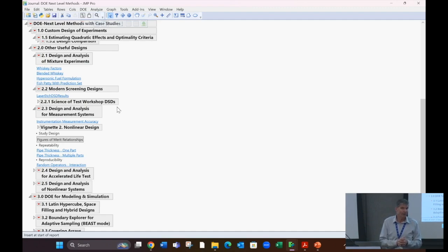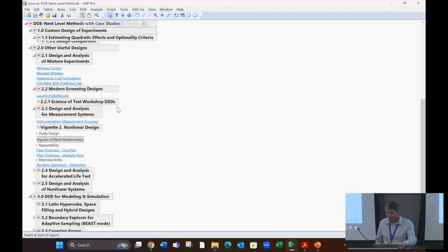And we would like to quantify how good our system is, right? A lot of people in the DT world in particular are very much on top of their gauge repeatability and reproducibility. Repeatability is, if I measure the same thing, how consistent am I? Reproducibility is, if John and I are measuring the same thing, how close are we? It might be that John always seems to measure about 20% higher than everyone else, or there's some bias out there. So by way of introduction, I think it's easiest to look at an example of this.